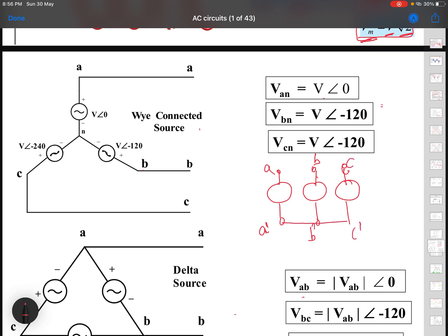What I can do is short out these 3 voltage sources together and transfer these 3 to the load. So only 3 wires would be required, and this remains here, and that is called Y connected or star connected sources. So my sources get connected in star, and this becomes a reference point, or what you call neutral. This is what is drawn here.